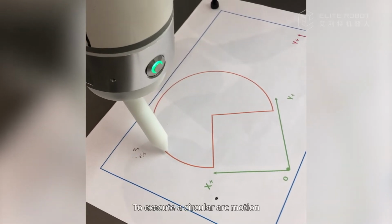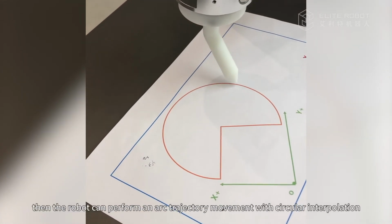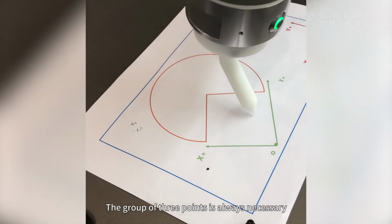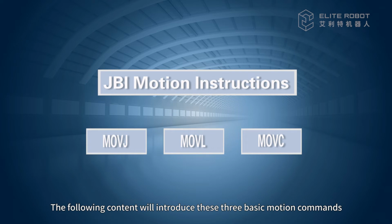To execute a circular arc motion, teach 3 points with the arc motion command. Then the robot can perform an arc trajectory movement with circular interpolation. The group of 3 points is always necessary for any arc motion command applications. Incorrect programming formatting will cause the arc motion to fail to execute, and the system will report a fault. The following content will introduce these 3 basic motion commands.